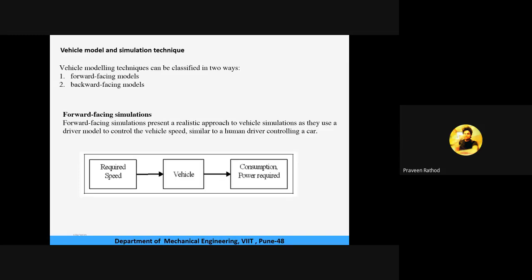Okay, so the source of power of BEV is an electric motor, we know that. Okay, and some of the appropriate models we are going to use, that is the driver model. In that we have a torque as well as a mechanical braking signal. So this torque from the motor is passed through the model of transmission and then applied to the driving wheels.